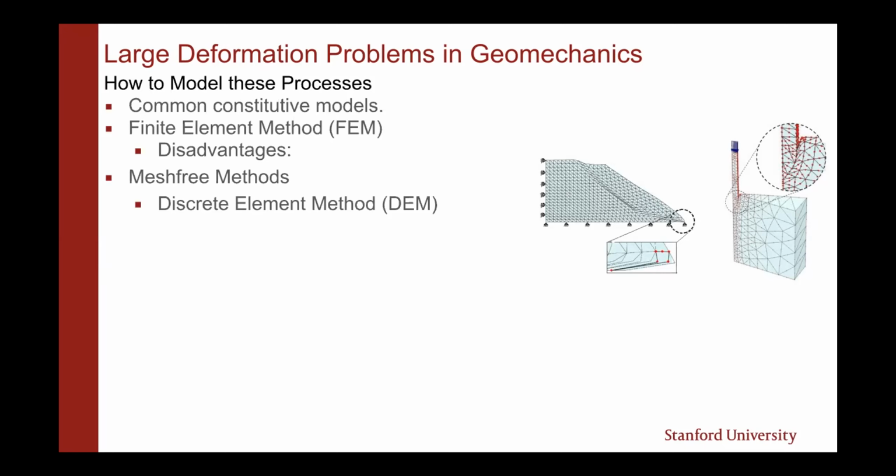But this tends to be very computationally intensive, so we prefer mesh-free methods which actually abide by the continuum assumption, such as smooth particle hydrodynamics. The advantage of mesh-free methods is not only that they do not have mesh entanglement or any of these issues when dealing with large deformations, but they also handle discontinuities naturally, essentially.